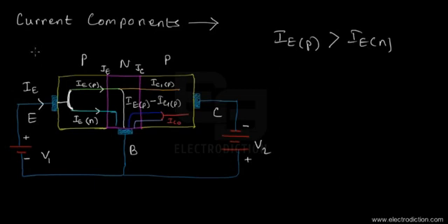And finally what will happen is that this IC1 current component due to the holes, and of course the reverse saturation current component denoted with the symbol ICO, taken together, would give us the total value of the collector current, which should come out of the collector terminal itself. So I'll just call it IC over here. And now also due to the recombination processes, a component of the current would go into the base over here, as you can see.